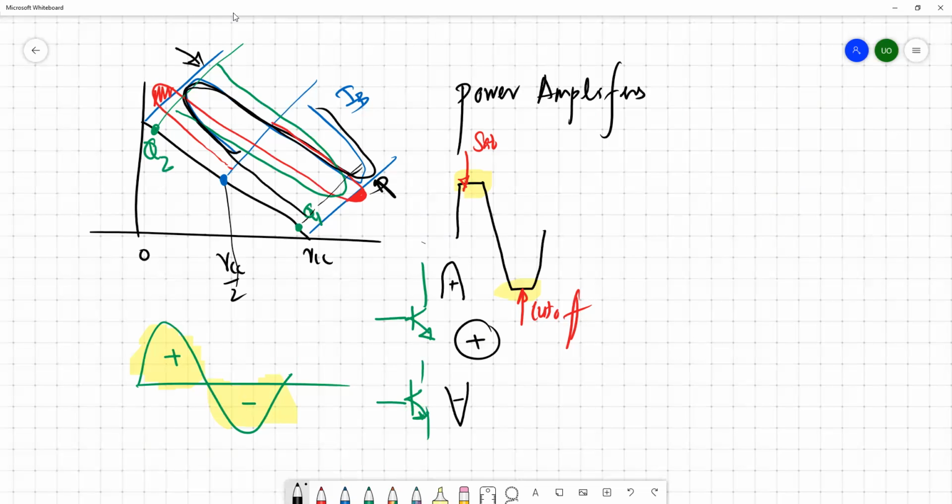analytically, and through this analysis you can give a hint about the operation of the transistor with these parameters, whether this kind of input can be managed or not. So do we need a separate solution, or can we manage with the given transistor, or do we need to go for a different transistor? Do we need to adjust these resistors and supply voltages, or do we need to fine-tune the Q point by shifting the load line in a different phase? So this kind of discussion can be made with these simple concepts.